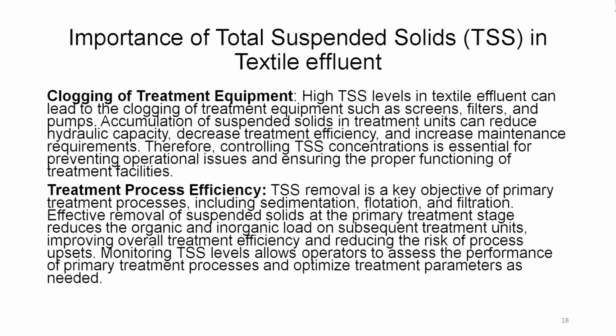Monitoring TSS levels allows operators to assess the performance of primary treatment processes and optimize treatment parameters as needed. So, you see, at every level these suspended solids need to be removed, and particularly at the primary level.